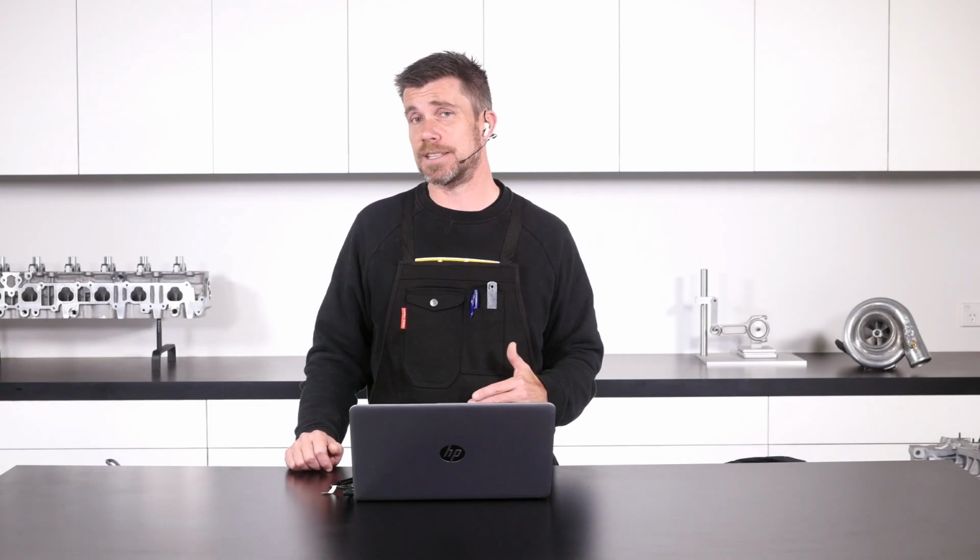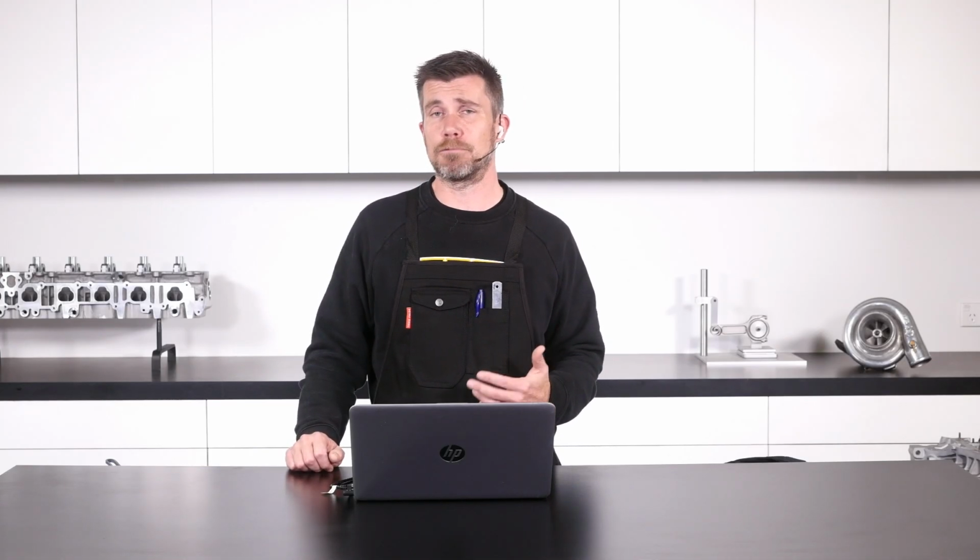If you try and put a really aggressive naturally aspirated cam profile into a turbocharged engine running a small turbocharger, it's simply not going to work. The high exhaust manifold back pressure coupled with the overlap and duration of a really aggressive cam just doesn't work. So when you get that ratio down and your exhaust manifold back pressure that much lower, you can start to see massive improvements in the power levels you can get out of these engines. Flip side there though, of course, if you're running a really large turbine wheel and exhaust housing AR that you're likely to see in a drag application, then you're going to get really poor boost response.